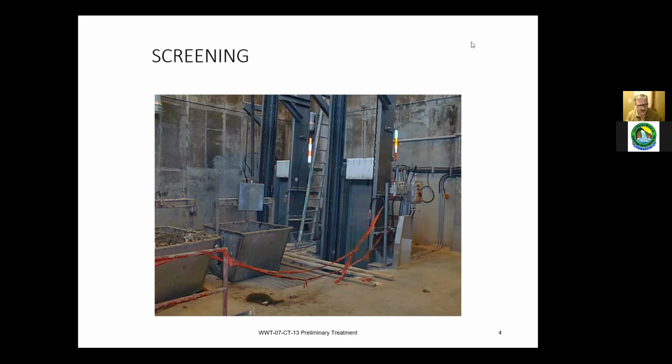Most of those will be on the inlet. Yeah, usually on a collection system. Collection systems are designed to get everything to a treatment plant. So a lot of times trash racks, whether mechanically or manually cleaned, will be out in the system. You want to remove tree limbs and any large debris before they try to get through a lift station or down the system. So you want to remove them there.